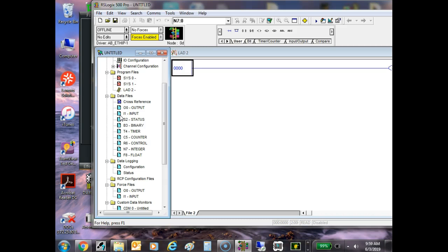On your older PLCs, RS Logix 500, this is set up for you. Some of your newer PLCs, like the MicroLogix 1100, you can add to this. It's got more memory in it. I think this 1100 has like 100K of memory in it. So what that means is it's got some extra memory in there, so if you need more counters, you can specify more counters. And we'll look at that because these are limited because the memory is identified, right? We'll talk about that as we go.